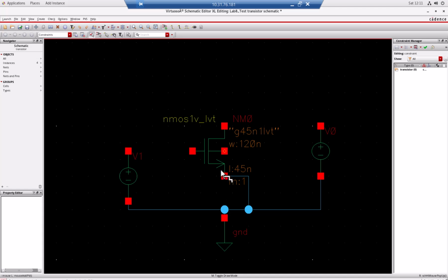Now I don't want to connect them together because I remember Cadence will give me an error if I have a node that is connected to 4 lines. Okay, so they're still the same terminal. How about the body, right? We did not discuss body much, but as we discussed in the high frequency simulation, the body in our class is usually connected to the source or connected to the ground, right? So I just connect them together.